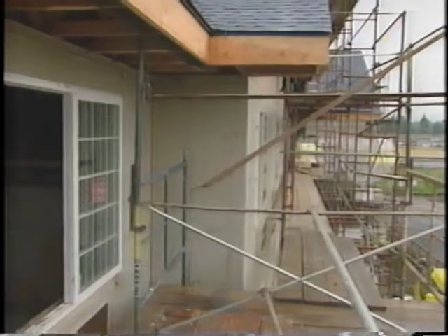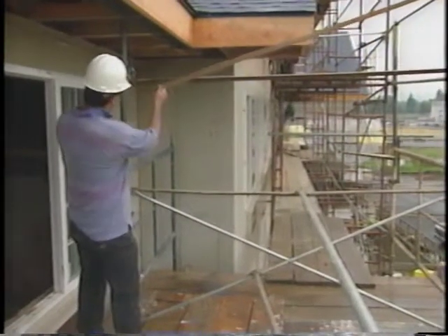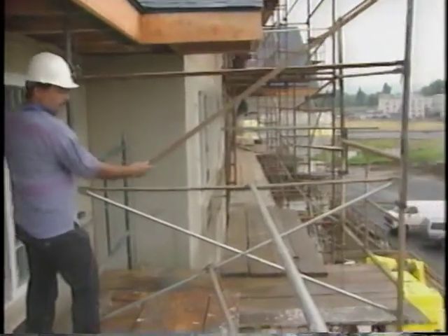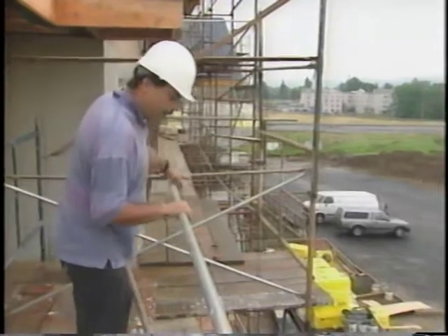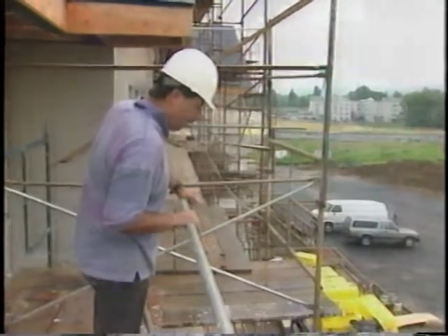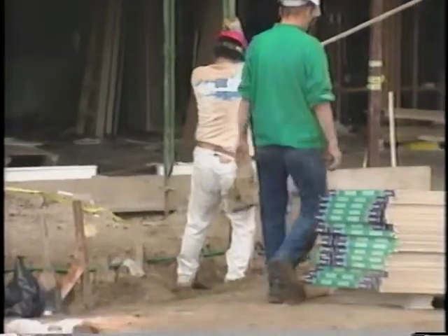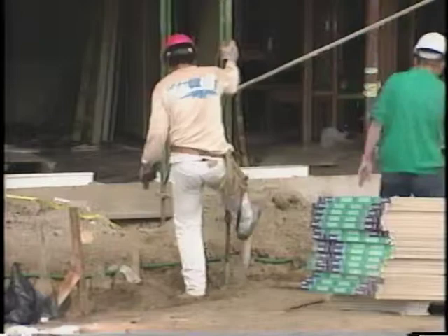If you notice any structural damage, settling, or movement of the scaffold, damaged planks, missing ties, or anything else that affects the integrity of the scaffold, report it to your supervisor. Do not make alterations or move the scaffold without approval and under the direction of a competent person.